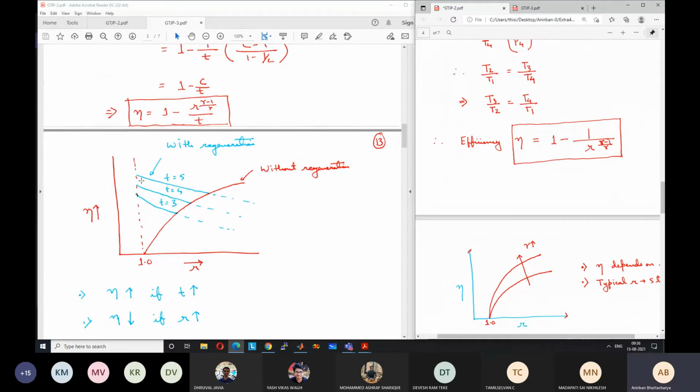So what is then the harm in operating with this high efficiency at a pressure ratio of 1.2? You have to think logically. We have already discussed this in detail yesterday and today. Turbine work will be very small. Overall, the work of the cycle itself will be very small, right?